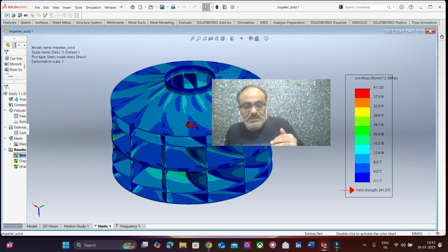Such situations can occur randomly. All those random loadings are acting on the chassis, so there is a probability for stress to accumulate. In order to reduce that stress accumulation, or for the stress to dissipate, certain holes are provided on the chassis. Those are the hotspot zones where the stresses need to be relieved.